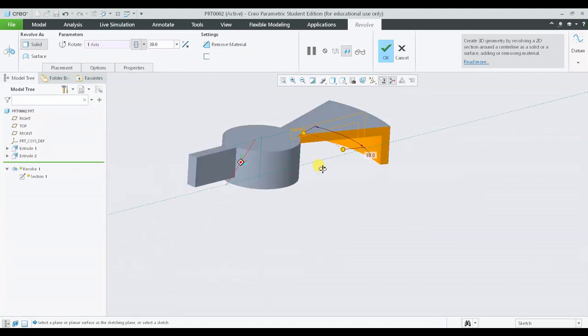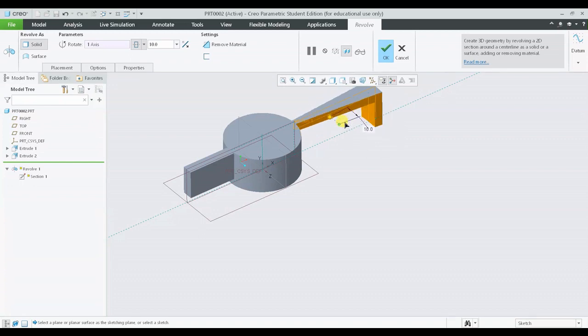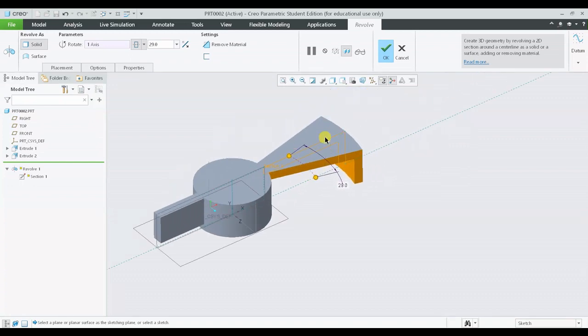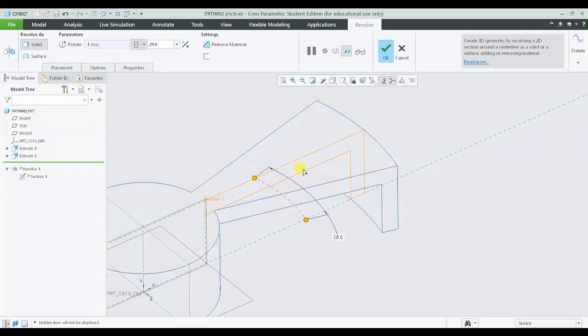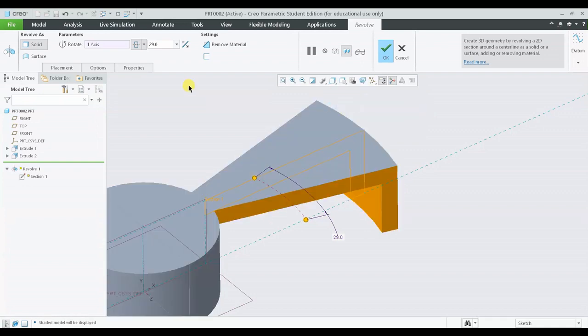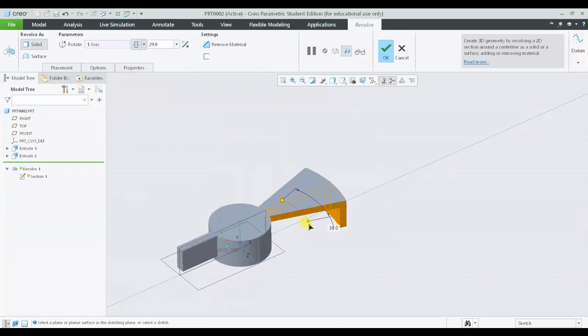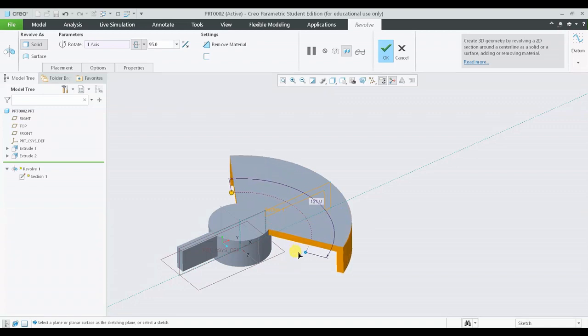You can see over here, initially my sketch was drawn at this particular location. I hope you can visually see the particular sketch over here. So whenever I have clicked on the Revolve option and I have chosen the symmetry option and the common dashboard options, I will be able to adjust the revolution symmetric on both the sides.